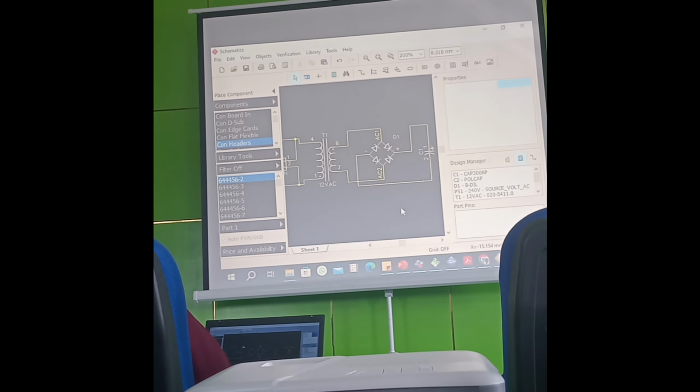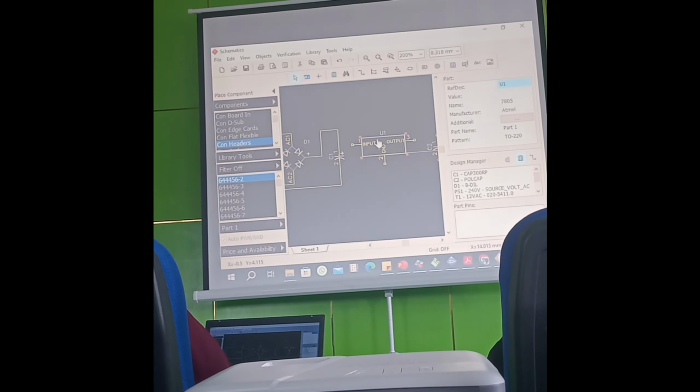Okay. So now we move to the next component. Let's drag this up like this. So now this is going into the input. Am I right? Then this capacitor, what's the value? 1000 uF. Most times we use 1000 uF 25 volts. There's a formula to calculate this capacitor.